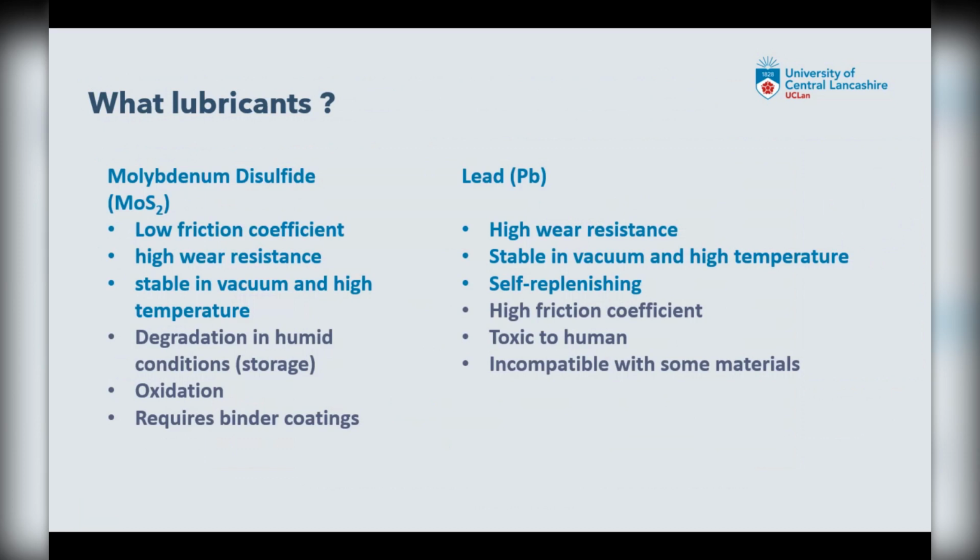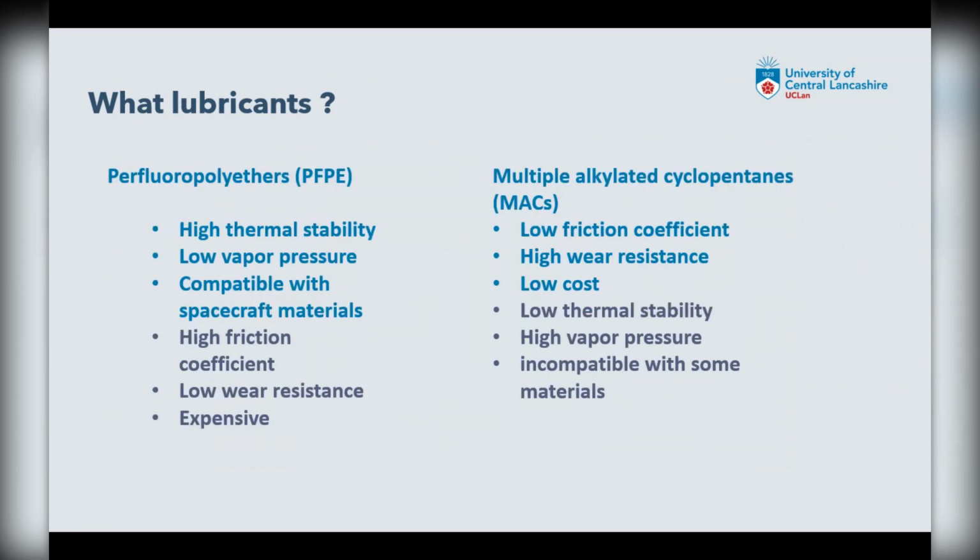The other one I should mention was commonly used, but now it's not used, because lead was commonly used. It has very good properties. It is self-replenishing, so it's kind of servicing itself, but it is toxic to humans. So when we store and test this spacecraft in laboratories, it's hazardous. I think lead is no longer on the list. Okay, so PFPE is a new star, and it's used frequently now.